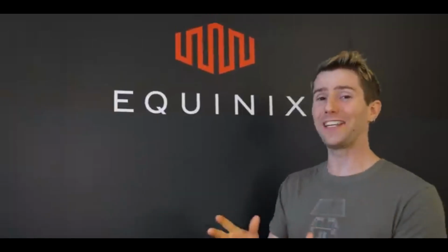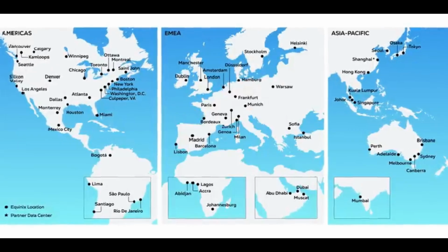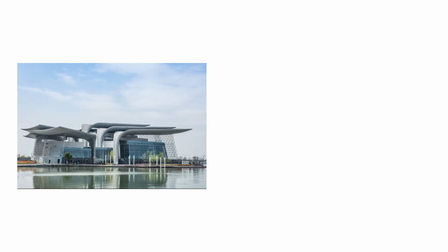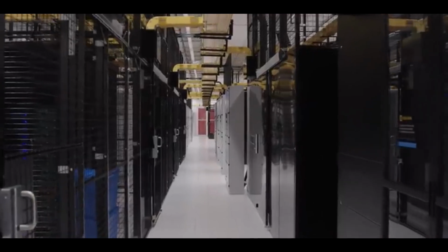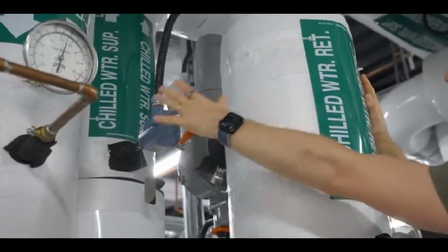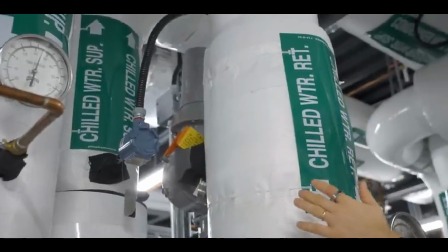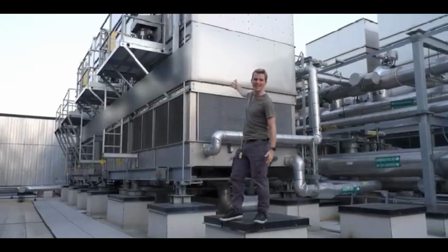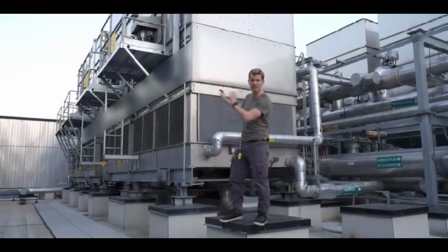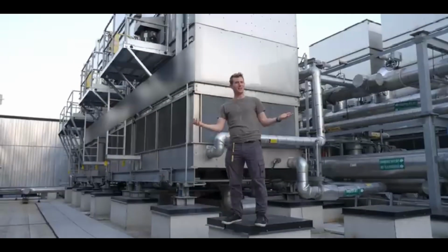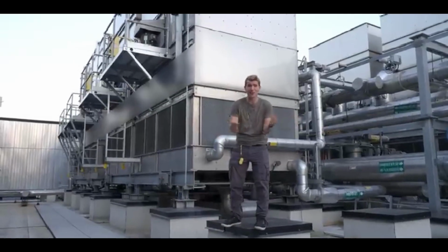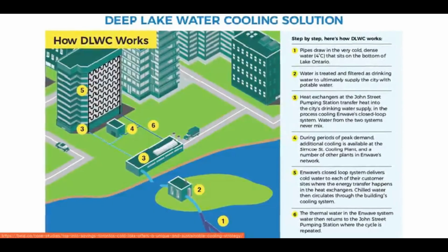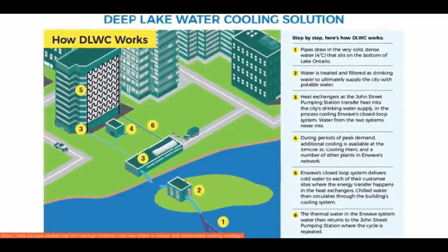One such company is Equinix, which is experimenting with this idea. Their servers work a little like a nuclear power plant, where all the servers are essentially cooled by lake water. The servers are placed inside watertight cages, and chilled water and coolants are flowed through them. Heat exchangers are then used to dispel the heat into the lake in a controlled way. This method massively reduces electricity costs for cooling and also helps with sustainability, since natural water resources absorb heat more efficiently than just blowing air with giant fans.